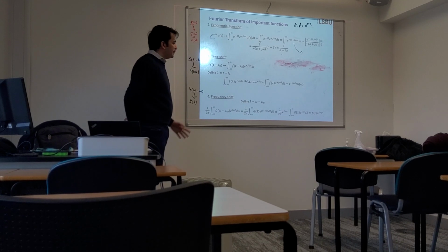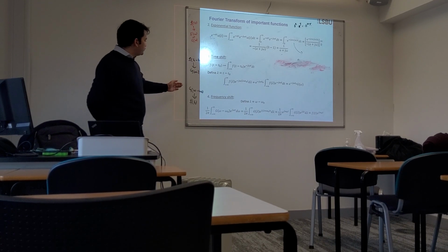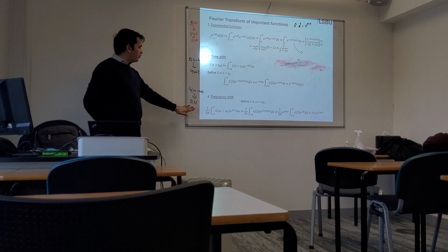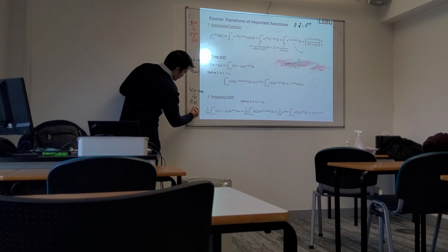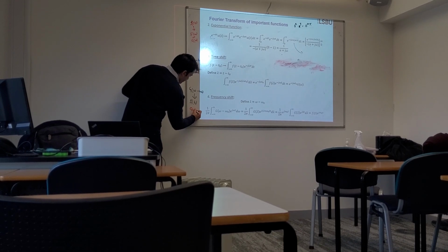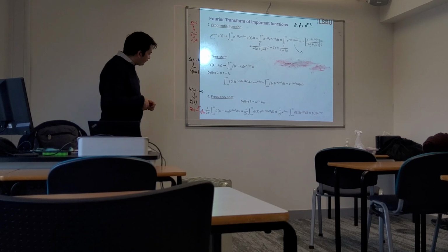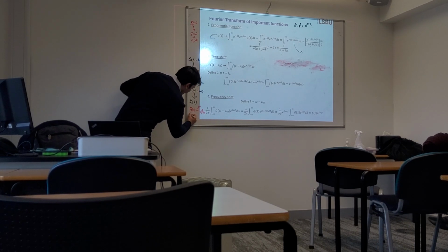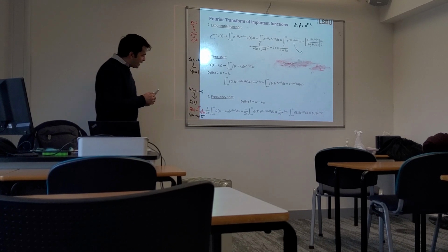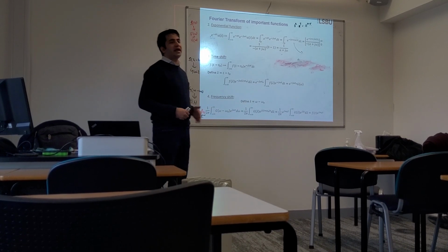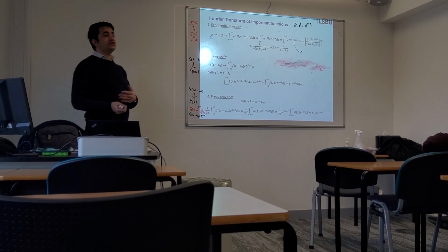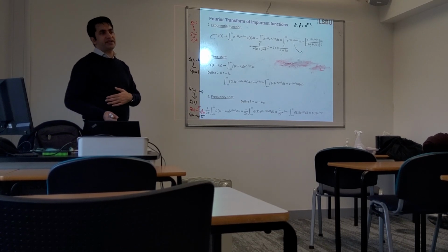So it means that if you have a shift in the frequency and you want to find the time function, you know that for g omega the Fourier inverse is f of t. If someone asks to find the Fourier inverse for omega minus omega naught, you can simply take f of t, multiply it by e power plus j omega naught t, and you can say that this is the time domain function for this equivalent frequency shift signal.